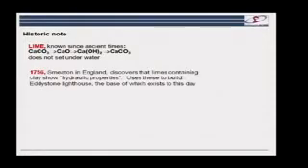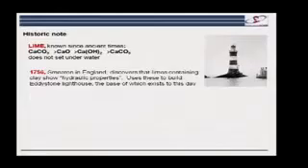So in 1756, Smeaton, who incidentally was the first person to call himself a civil engineer, came across the fact that if he had lime which contained clay, then he got what's called hydraulic properties. Hydraulic means that it sets underwater. And he used this to build the Eddystone Lighthouse. This is a picture of the original Eddystone Lighthouse, and mainly he used this in the foundation here.